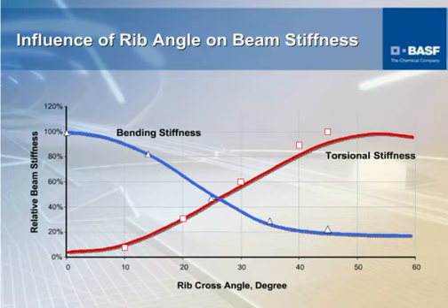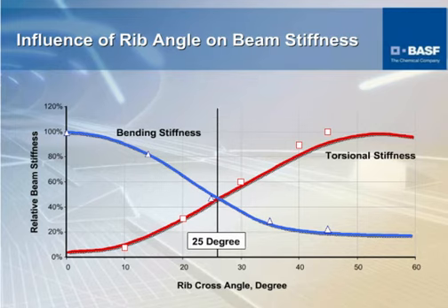And some clutch pedals are totally in line, seeing pure bending. But if the pedal is offset from the connection rod, that will make the pedal and that whole rod want to twist. And that would be seeing bending and torsion. So if that was the case, basically your optimal rib pattern would actually be 25 degrees or a little bit more beyond 25 degrees. And it would probably be a W or an X pattern, as we'll see here shortly.